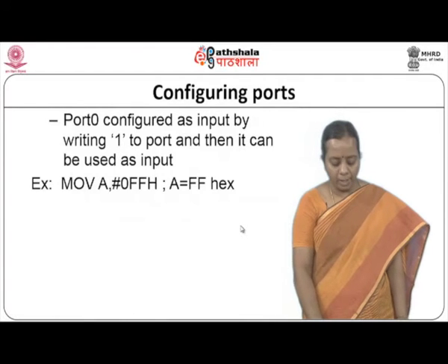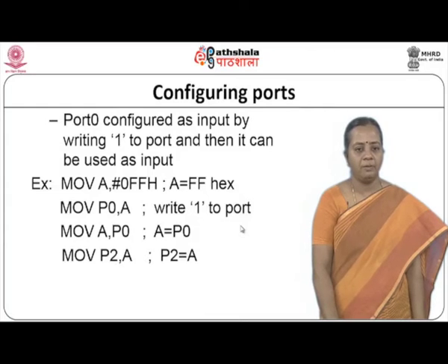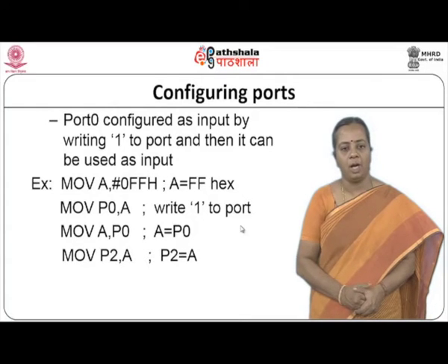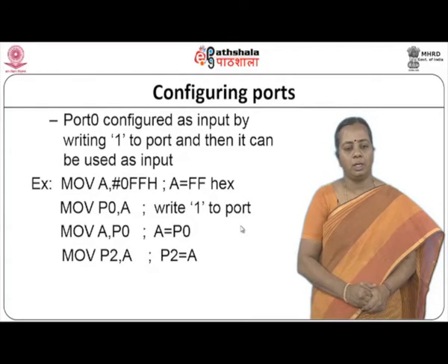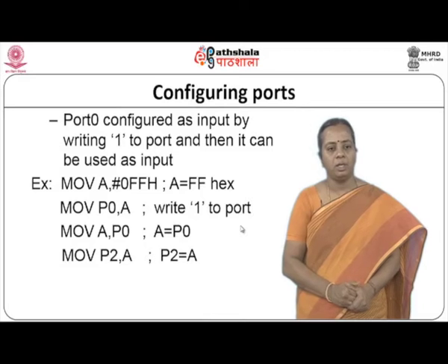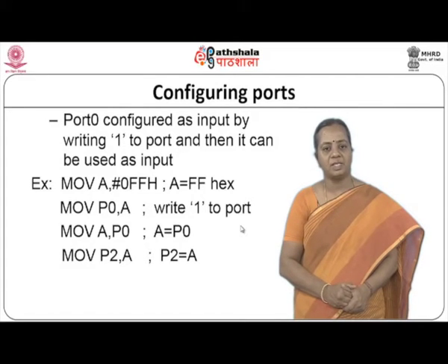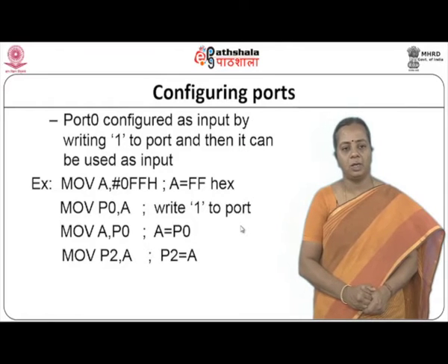Now, this is a simple program segment where I configure a particular port as an input port and read it. This is an example code, a part of a program, where port 0 is configured as an input port by sending 8 ones, which I can call FF.